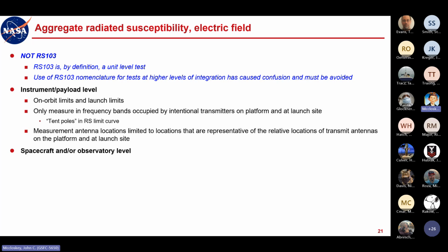If you're already doing 4, another 5th one is, if you're looking at a 6-hour day versus a 7-hour day, in the grand scheme of things, that's a drop in the bucket. So with RE, if you're in any doubt, throw in the extra antenna position. RS is much more time consuming, and you want to be much more deliberate about your antenna positions and just make sure that each one is truly value added.